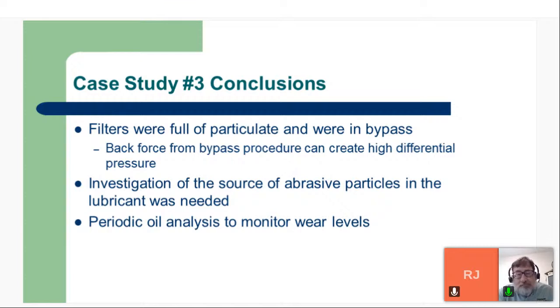In fact, this morning earlier, I was in a conference in Germany remotely, and Mark Redding of Poseidon was talking there about when they use the online sensors in wind turbine gearboxes, they're able to see how the wear rates are, and they're very much variable. There'll be a period of operation where there's very little wear being generated. Then suddenly the operational conditions will change, the loading conditions will change. In that case, the wind will change, and then there'll be a short period of high wear rate generation.